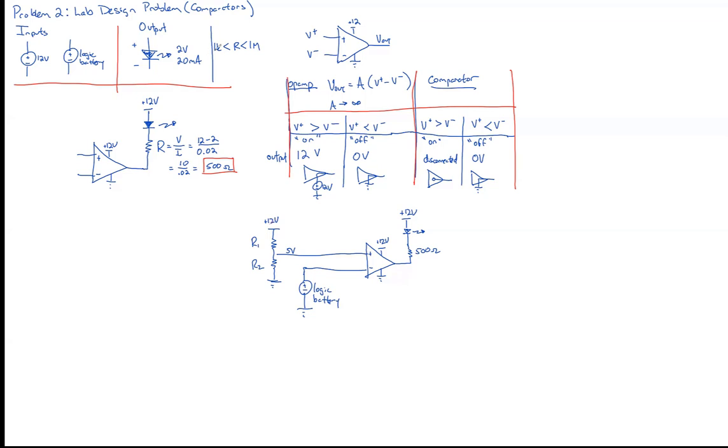On the other hand, if you go the opposite way and make the resistors ridiculously big, hundreds of giga ohms, then just simply touching that resistor is going to put finger oils on the outside and change its resistance, so that's a bad idea. But this range from 1K to 1 mega ohm still gives you a huge range of values to work on.